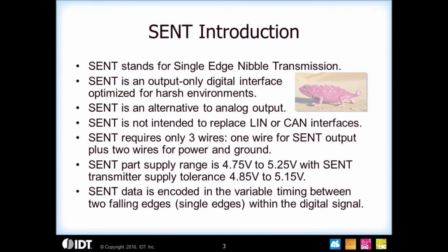SENT stands for Single Edge Nibble Transmission. It's an output-only digital interface. So because it's output-only, it's really not an alternative to LIN or CAN in an automotive application, but is seen more as an alternative to an analog output.